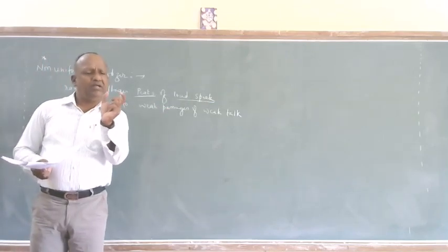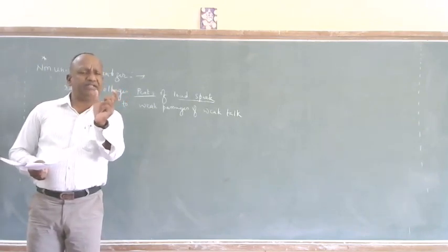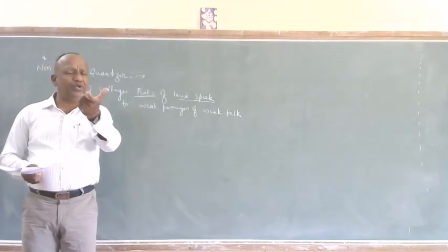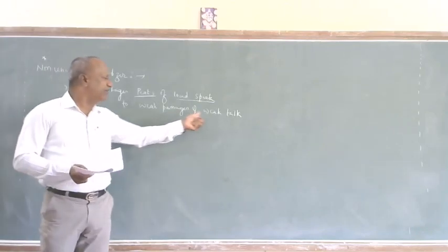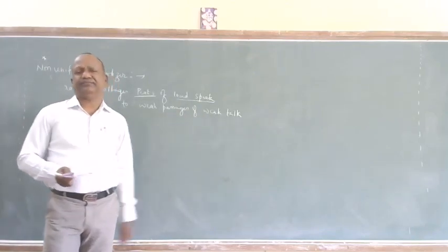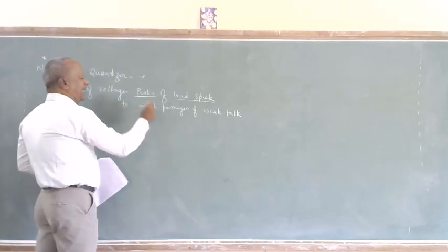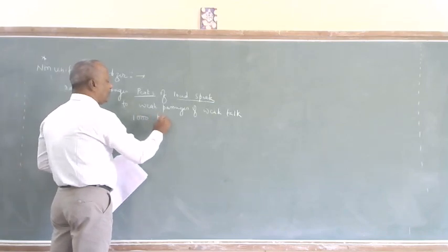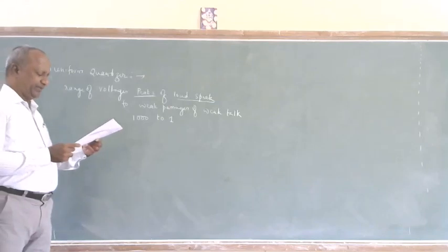When I talk, I use word by word pronunciation, so there is a transition from one word to another. In that transition there is no information to be generated, but there is a sound, and that sound has a very weak amplitude. So the peaks and the weak parts have a range in the form of 1000 to 1.